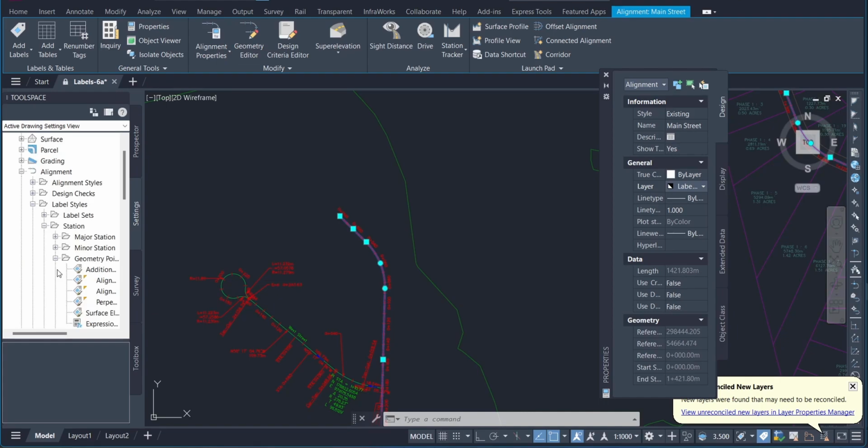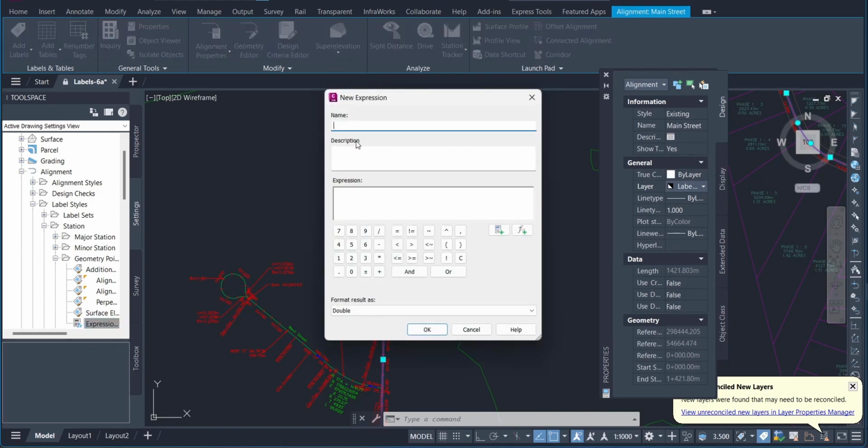Click Insert Property. Click Instantaneous Direction. This property will be used as the basis for computing the magnetic direction. In the New Expression dialog box, in the Expression field, use the keypad to enter the formula. Note: use the button to enter pi. The completed equation looks like this. The expression includes a conversion from degrees to radians because Autodesk Civil 3D uses radians for all internal angle calculations.